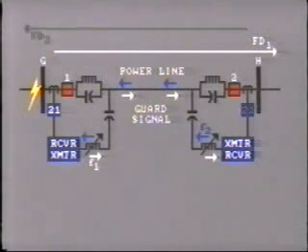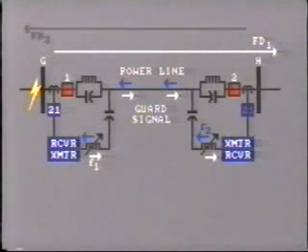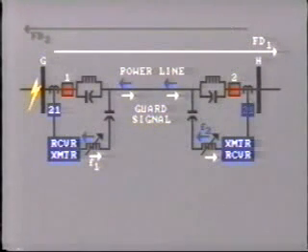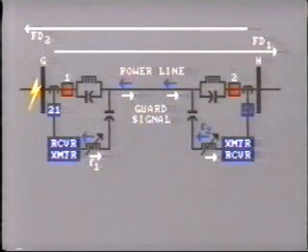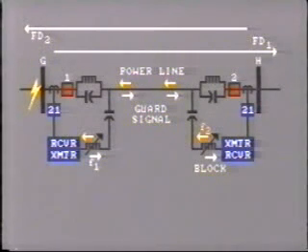However, the fault detector at bus H does register the fault because, remember, the relay is set to overreach into the next section. However, this will not trip breaker number 2 because of the blocking signal being received from terminal 1. Operation of the fault detector at bus H also keys the transmitter at station H to change its transmitting frequency from the guard signal to the trip signal.